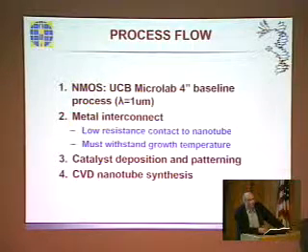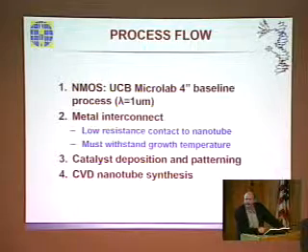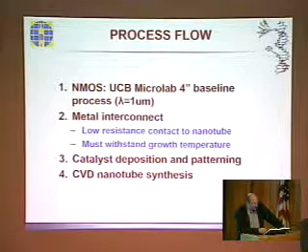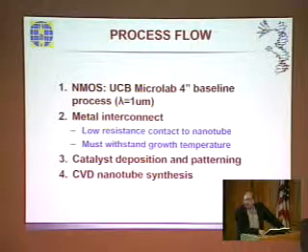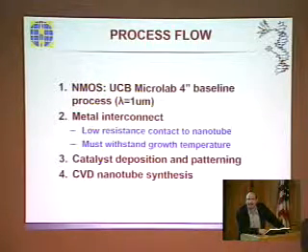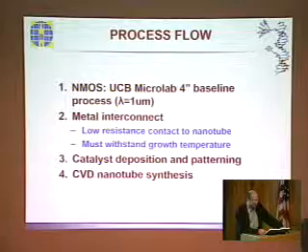So this is why it's absolutely crucial for us to have CMOS capability in our lab. It's not good enough for us to just get access to industry, like MOSIS, foundry type CMOS. In order to really make progress in this field of integrating silicon electronics with any kind of nanotechnology, the ability to have in our own microlab CMOS capability is crucial. We have a baseline 1 micron process that we can have access to in the microlab, and that's the one we're using. And the key place we had to focus our attention was on getting a good metal interconnect that would allow us to interconnect together a large number of silicon transistors, as well as getting good contact between silicon and carbon nanotubes, and make that integrate with the nanotube synthesis.